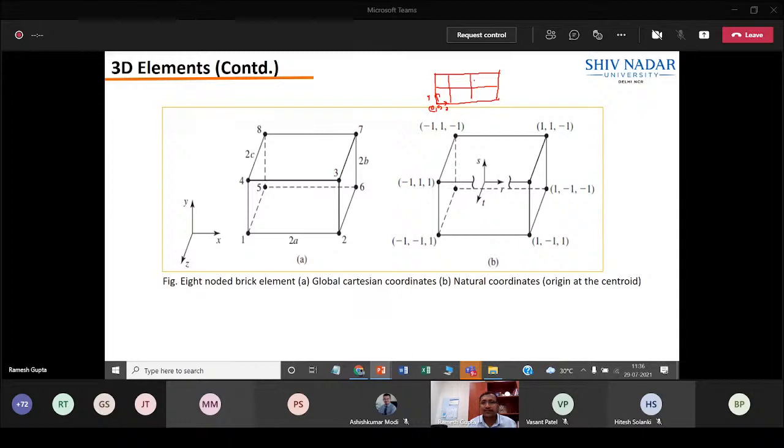So what I will do is take one element, or one tile, out of it, and find out the stiffness of this element. Then I will map from here to here by changing its geometric location. That means I don't need to calculate the stiffness every time. Rather, I will create a database for one variety of the element, and keep on calling that. It reduces your computational effort. You are just calling a function with a stiffness for one variety of element, and giving the input in such a way that it represents the stiffness at different locations.